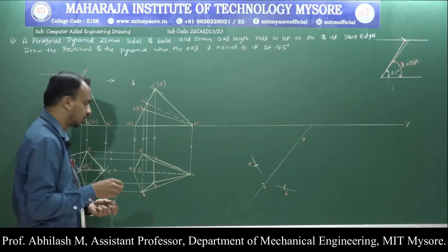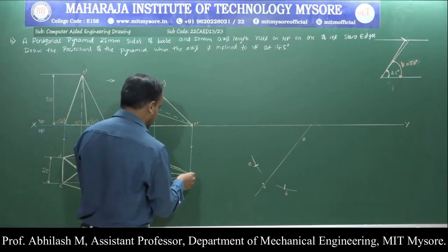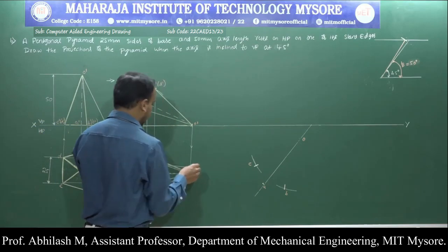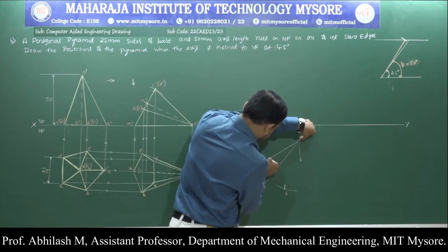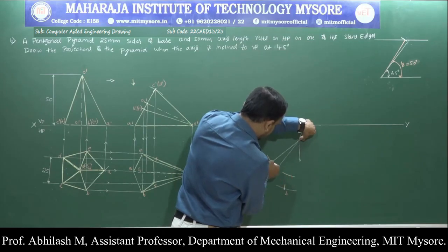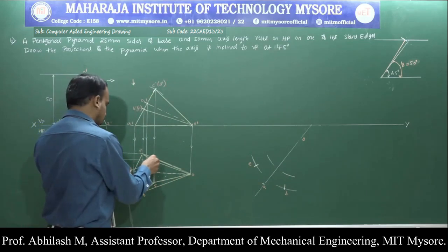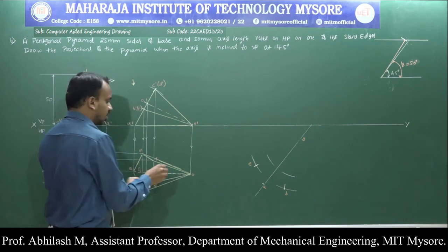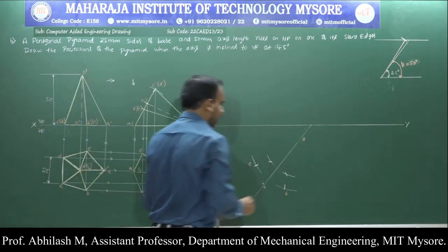What is the next thing that I am supposed to transfer? I am supposed to transfer O to C and O to D. So measure from O to D and cut an arc. Similarly, the other point, that is the point C. In order to complete it, measure from A to D, and similarly it will be the same for the point C also.